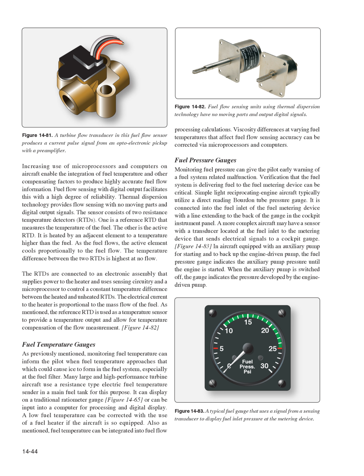The temperature difference between the two RTDs is highest at no flow. The RTDs are connected to an electronic assembly that supplies power to the heater and uses sensing circuitry and a microprocessor to control a constant temperature difference between the heated and unheated RTDs.